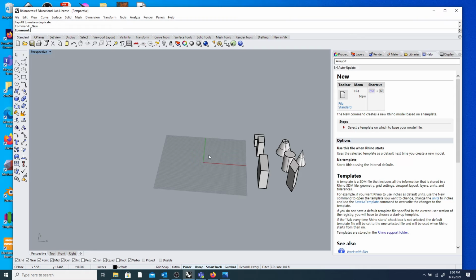So your construction plane, in Rhino's terms, is usually abbreviated as C-plane. There's a variety of ways to reorient that. As we know, everything that we draw usually starts out on the C-plane. So you can orient your C-plane to object surfaces. You can define what angle you rotate it to. You can move it wherever you need, to make your job of constructing either a three-dimensional form or a curve much easier.